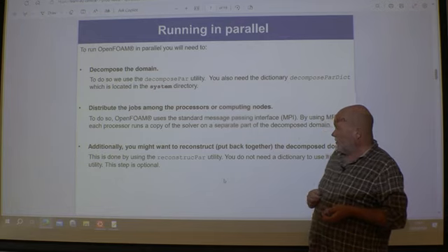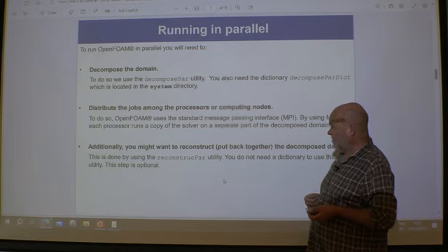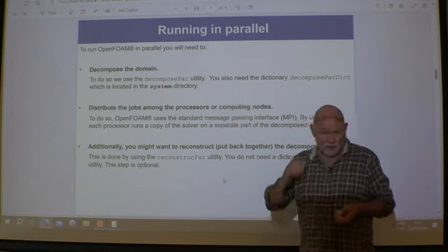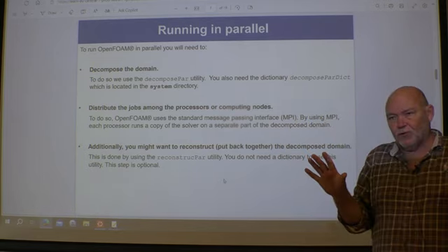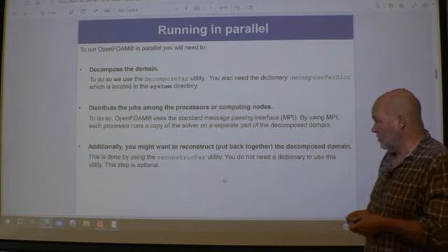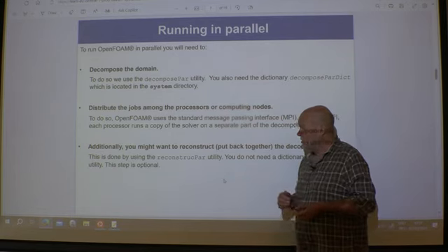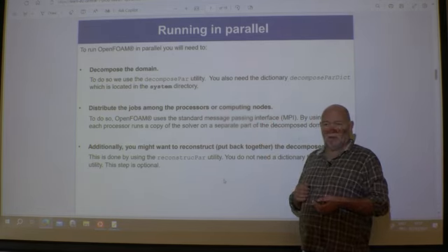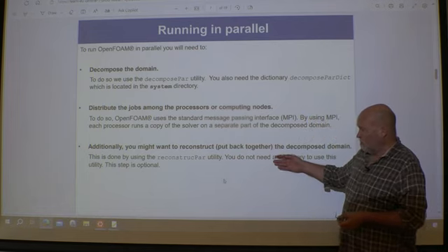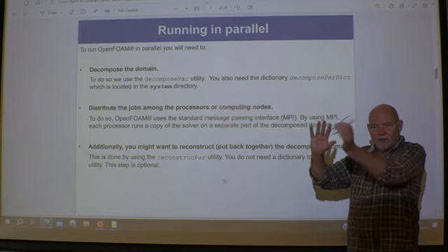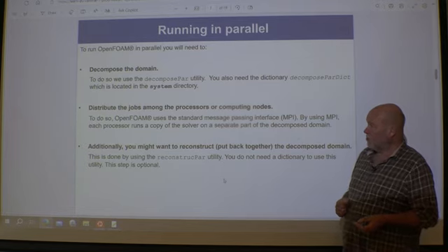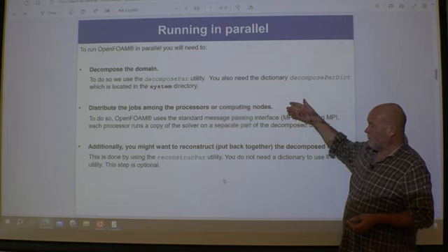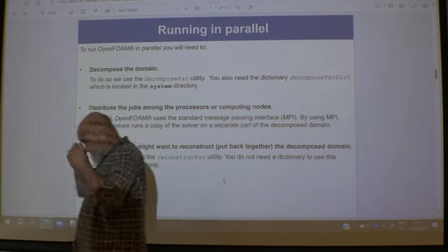And then when we are simulating, yes, we are using MPI. And then in the end, you will have a result split up into the number of processors that you have been using. So if you have, say, 4 CPUs, then you will not get one single result folder at the end, but you'll have 4 of them. So typically you want to reconstruct it. You want to glue all these different solutions together into one. Then we are back to what's normal, you might say. So 3 steps instead of just simulate. That is the classical setup.